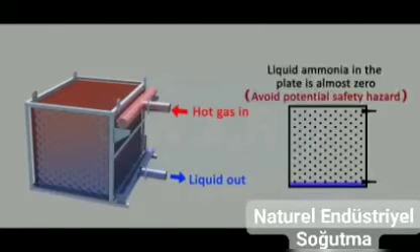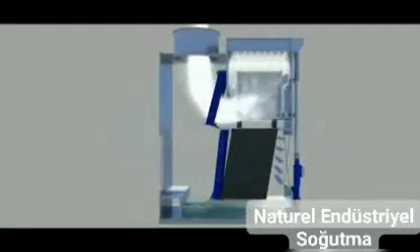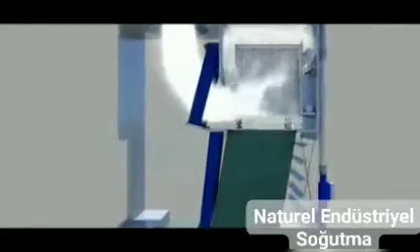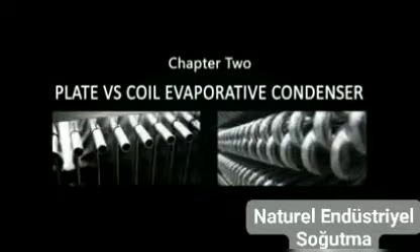The condensed refrigerant leaves at the bottom of each plate cassette and is collected in the lower header. This geometry results in a reduced charge. On the water side, the majority of unevaporated warm water directly flows through the efficient PVC padding, which gets cooled down by side entry fresh air. The cooled water drops into the lower basin for recirculation.